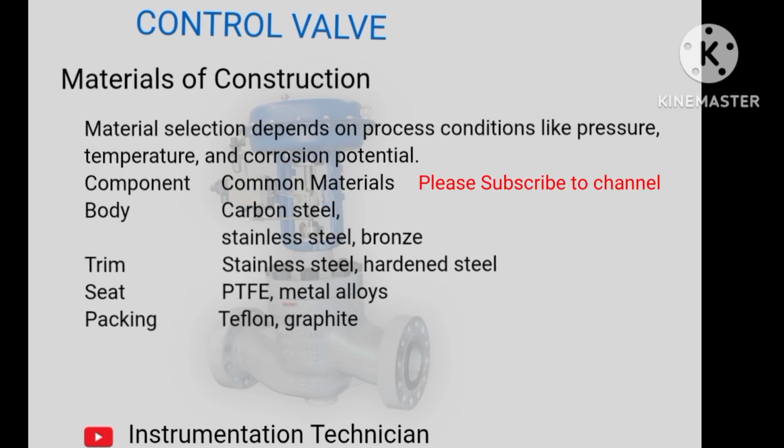Materials of construction. Material selection depends on process conditions like pressure, temperature, and corrosion potential. Component, common materials: body, carbon steel, stainless steel, bronze. Trim, stainless steel, hardened steel. Seat, PTFE, metal alloys. Packing, Teflon, graphite.